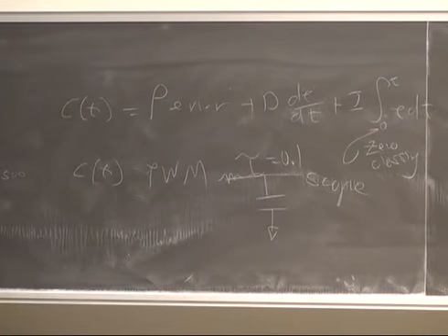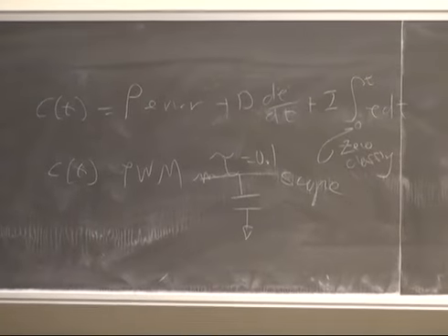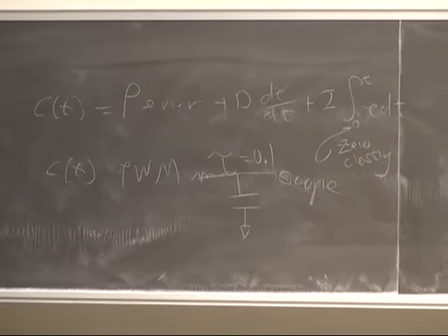That time constant is faster than the motor but slower than the PWM, so it's a good compromise. PWM maximum speed is about 1 kilohertz, and I would run it right around 1 kilohertz, not much slower. For the RPM calculation, you're going to have to convert the RPM to a PWM pulse and output it if you're going to put it on the oscilloscope, or you can put both of them on the TFT.